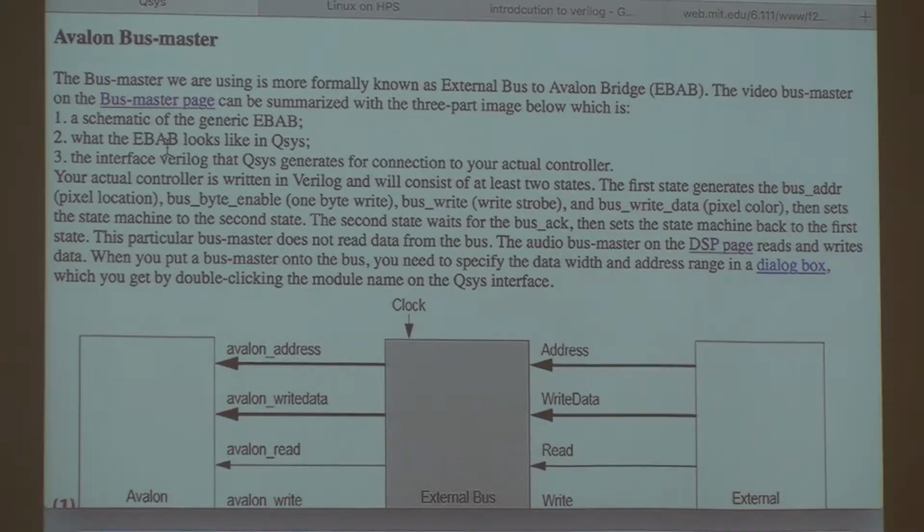You can give it bursty data because it has a 128 word FIFO on the input and output. But you have to read it often enough to keep those FIFOs non-empty. It produces data, it has an ADC input. It produces data that appears in a FIFO that you can read.